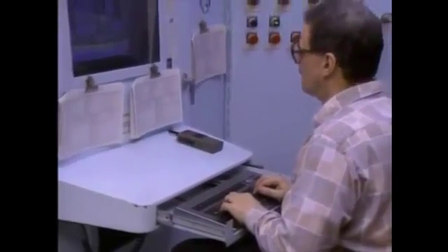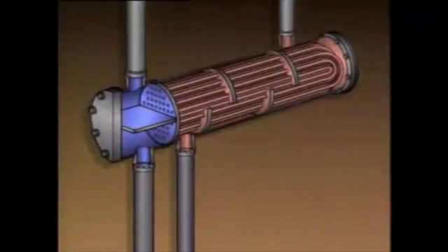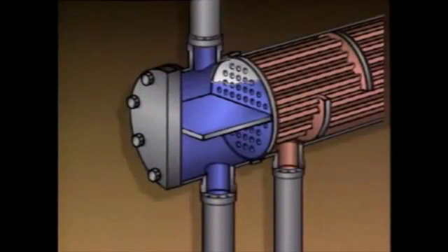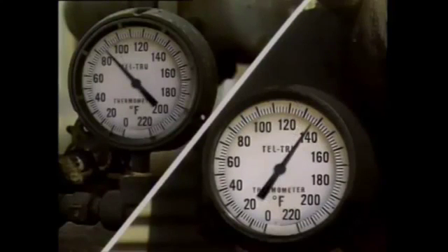No matter how air or other gases get trapped inside a heat exchanger, they can cause it to become air-bound or vapor-bound. There are several symptoms to indicate this. For example, when trapped gas blocks flow to some of the tubes, the outlet temperatures of the two fluids may change. This is because the gas is restricting flow into the tubes, and the restricted flow causes less heat transfer surface area to be available. The decrease in heat transfer surface area will cause the outlet temperature of the process fluid to increase, since less heat will be removed from the fluid.